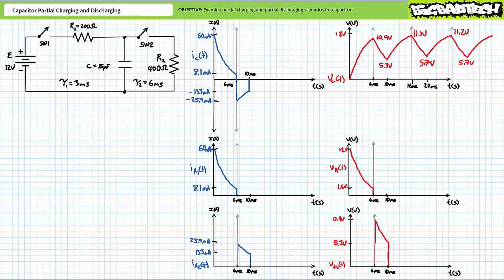The point of this extended example is to demonstrate that partially charging and partially discharging a capacitor isn't necessarily that difficult to conceptualize. In summary, derive the functions for the properties of interest as if it were to be a full 5-time constant charge or discharge, and then just cut the graphs off at the intermediate time of interest. Instantaneous values at the time of the switchover can be easily obtained by substituting in the time of interest.